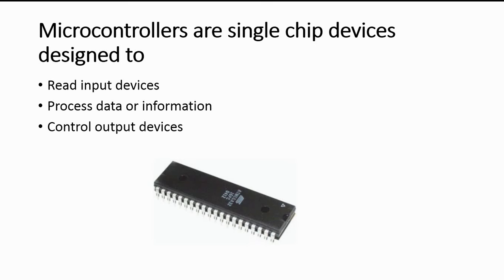But as time passed, solid state relays came into the picture. The solid state relays, meaning the semiconductor relays in which MOSFETs and FETs are used for controlling the switching operation. And the solid state relays provide the optical isolation that optically isolates the high voltage and the microcontroller. So they are preferred over the electromechanical relays.